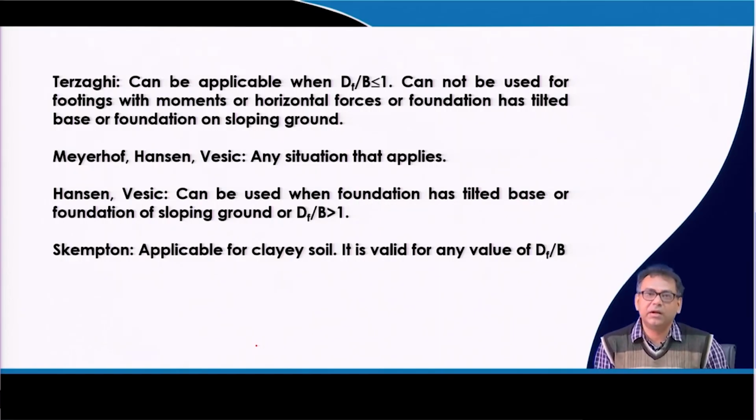So, now that means you cannot say which equation you should use always. No, there is no such condition, because it depends upon your requirement. In general, Meyerhof, Hansen and Vesic can be applicable for more or less all the cases, but Skempton is only applicable for clay soil, and in my next design problems I will prefer to use Skempton if the soil is clay soil.